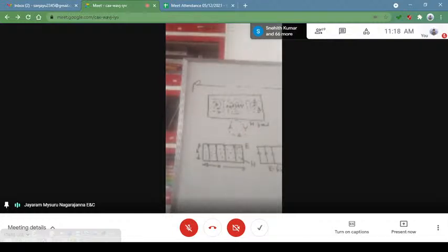And regarding that M and N, what they generally say is that they are called the modal numbers, which determine the order of the mode that is supported by the waveguide system. Some textbooks say that it corresponds to the number of maximum values that occur across the cross section of the waveguide.